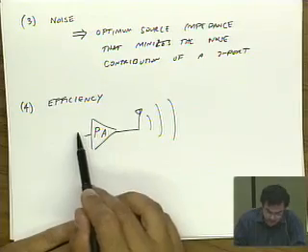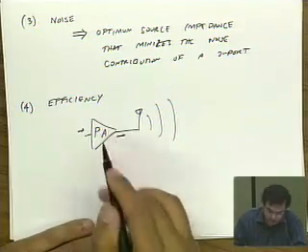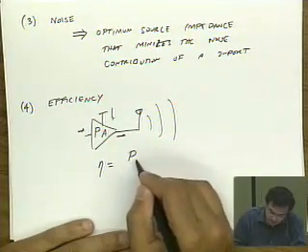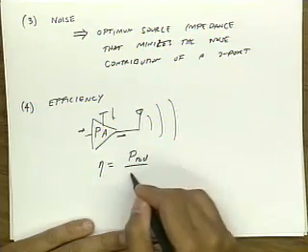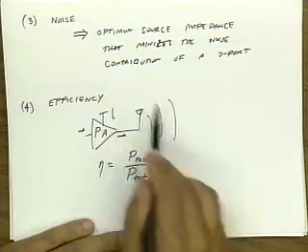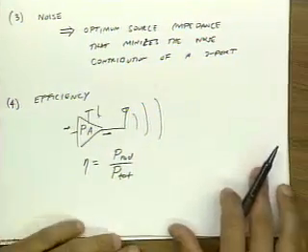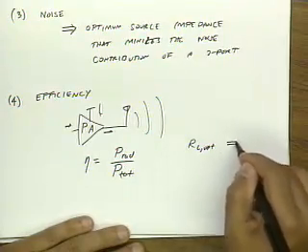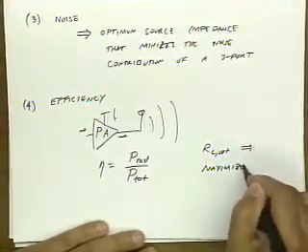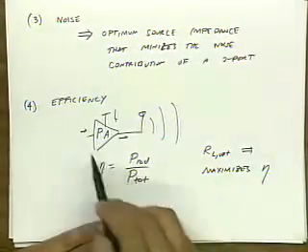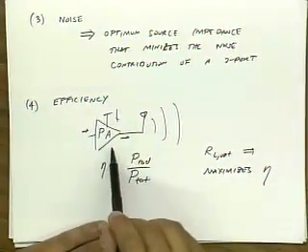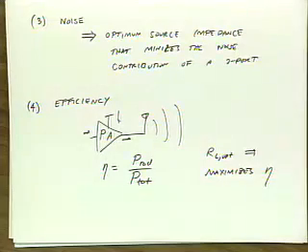So let's say the power gain is how much input power you put in versus output power, if you can improve the efficiency. Now the efficiency is the power, let's say, that we radiate versus the total power consumption in the system. And what we'll find in this course is, again, there is an RL optimum that maximizes efficiency. And so when you design power amplifiers, we won't be concerned with power gain, we'll be concerned with efficiency. So these are some 4 important reasons why we should care about impedance matching.